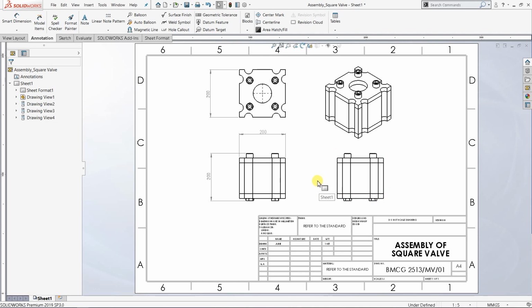Okay, you have to remember in the 2D technical drawing for the assembly, you are not advised to indicate all detailed dimensions, just enough to indicate the major dimensions such as overall height, overall width as well as overall length, as you can see on the screen right now. All right. So one more thing, once you already created this one, you might also indicate this isometric view for the assembly drawing as well.